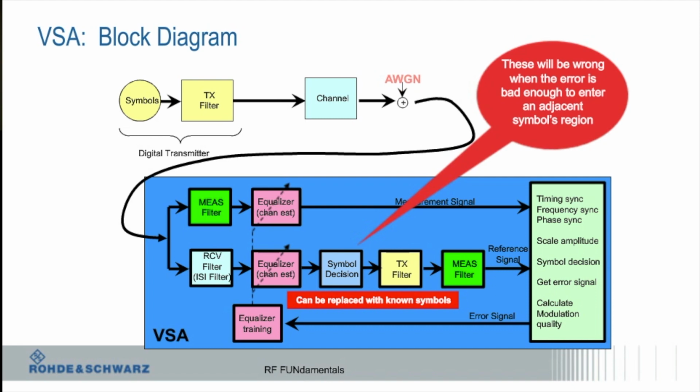So what they'll do is when you start a sequence, it's actually going to use known values, right? So that's why you'll see with a lot of these standards and things, it'll start out with what they call a training sequence. So they'll say, you know, for this certain period, first so many symbols or whatever, we're going to send this sequence. So it's looking for that. It's expecting that. And then it's using that to say, okay, I know this is what these incoming symbols are, and I'm going to mess with my equalizer and channel estimator to determine what my coefficients are to optimize what that input signal is.